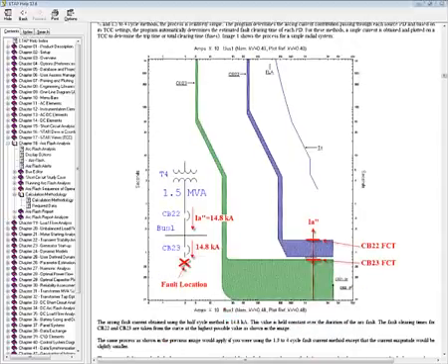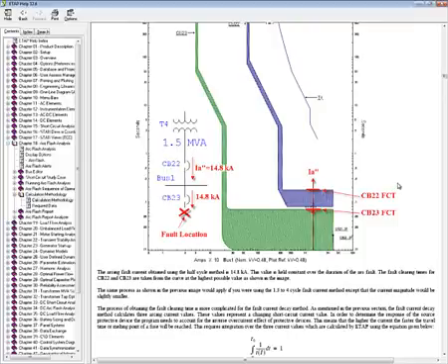The TCC curve that I have shown here highlights the example of the determination of fault clearing time using the 1.5 to 4 cycle method, or the half cycle method. This plot currently shows the subtransient current for a half cycle calculation methodology. As you can see, the operation of CB23 will be based on the upper band of the instantaneous region. Similarly, CB22 will be evaluated the same way, but with of course that time delay.